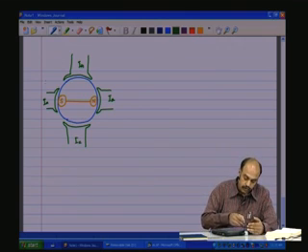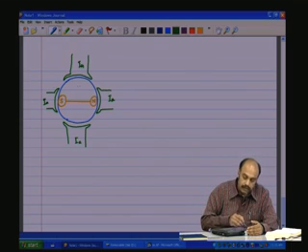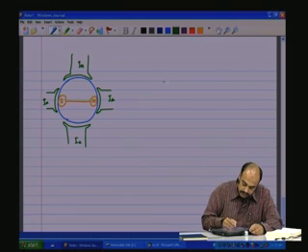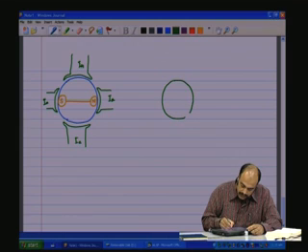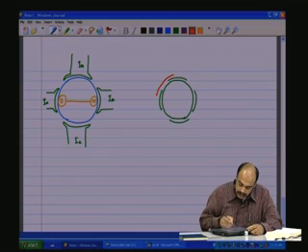And then there are four sets of other B phase which are tilted and shifted 120 degrees in axis, and then another four sets for the C phase. So they are shifted and placed in such a manner, just to indicate, so we have, let us say, the rotor. Let me say this is the A pole set, that is the A phase, and the B phase, let us say, is shifted 120 degrees.